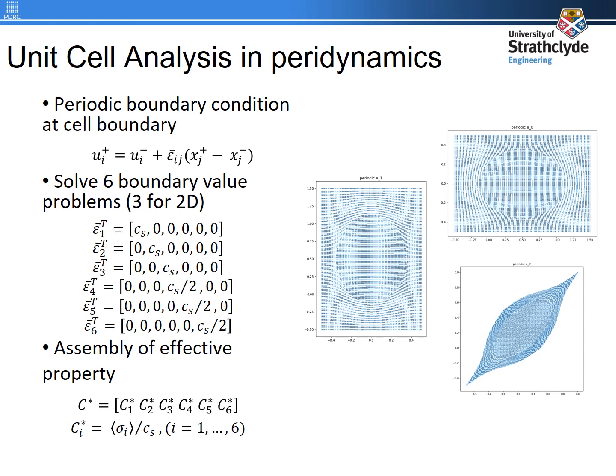Periodic boundary condition is sometimes mistaken by some who are not familiar with this topic for homogeneous boundary condition. Homogeneous boundary condition is a different kind of boundary condition which strictly defines the displacement at the boundary. However, periodic boundary condition only sets a relative position for each boundary pair, and the exact displacement value is not strictly imposed on any individual node.